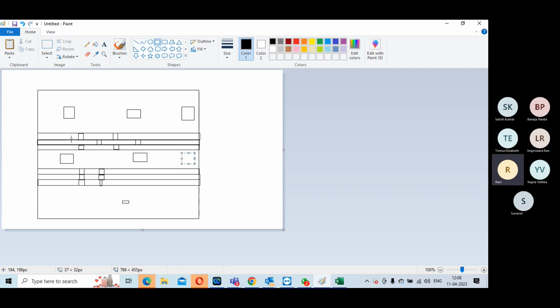You understand? So you can create the spare cell regions like this, and allow the spare cells in the matrix so that whatever cell I have, at least I know the maximum distance I have to travel for any connection is 100 micron. I should be okay. You understand? If I have got a logic over here, it is 100 micron, or if this is closer to this, 100 micron like that.